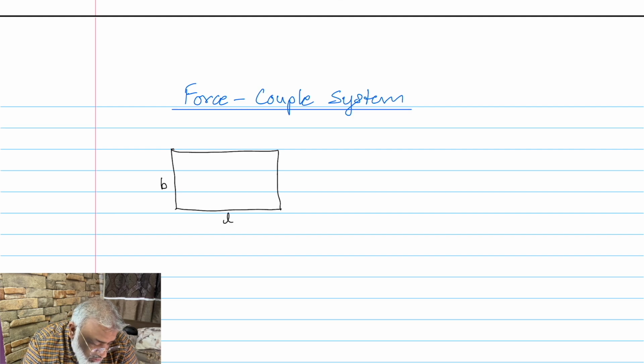So there will be a number of points on this body, and the four corners of the body will be, say, A, B, C, D. And I have a force F which is acting at point A. Now, say the situation demands that the force acting on point A needs to be moved to point D, but the problem should not change. The effect which this force F is causing on the body ABCD should not change. It should remain the same.